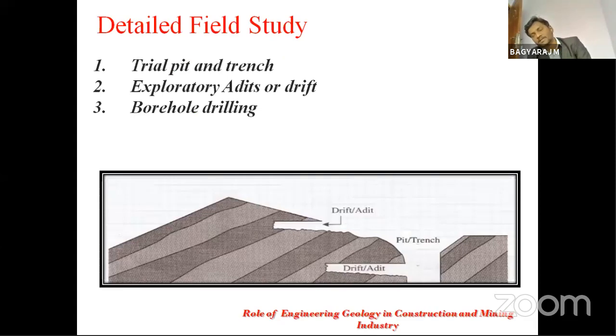Now let's come to the detailed field studies. As engineering geologists, we have to play the most important role depending upon the nature and size of the project. We go for detailed investigations which involve the services of different kinds of alignment for topographic, soil and rock types. We include subsurface exploration to see how the soil and rocks extend downward and what variations come.